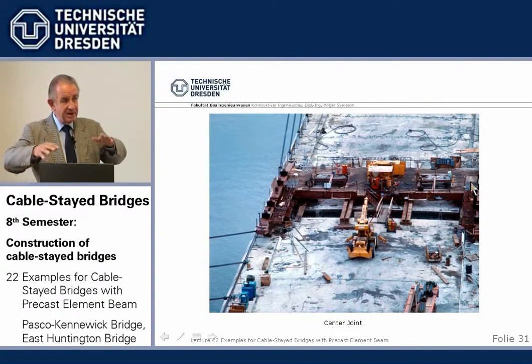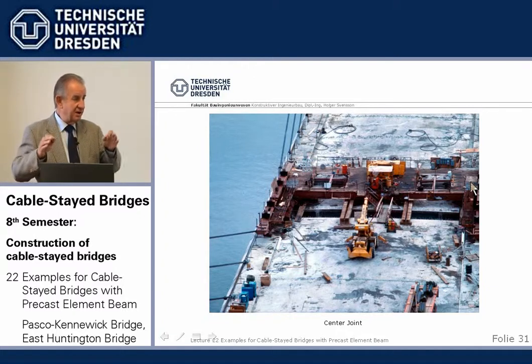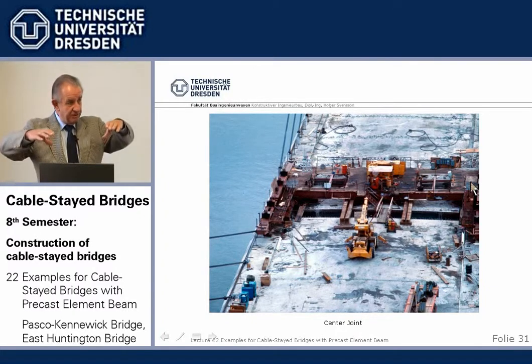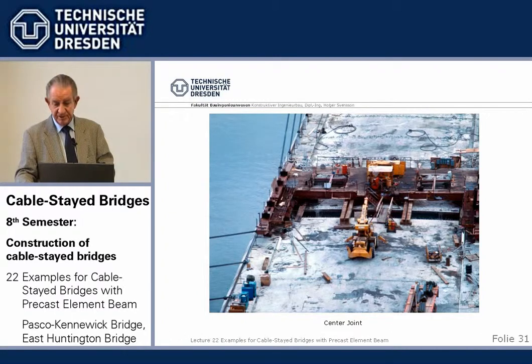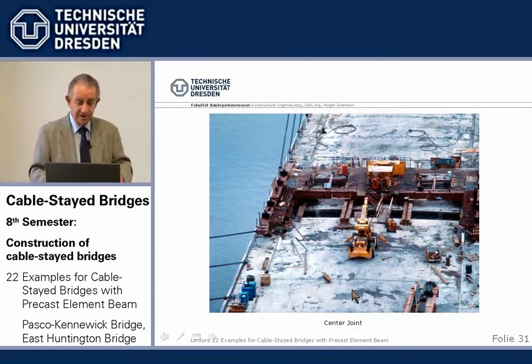Temperature, wind, and so on, and if you want to cure the concrete, it must be absolutely without any movement. So we fixed the joint with bridging it and stressing the Travellers on top, cast it, and then we have overlapping post-tensioning and reinforcement, and that was it.